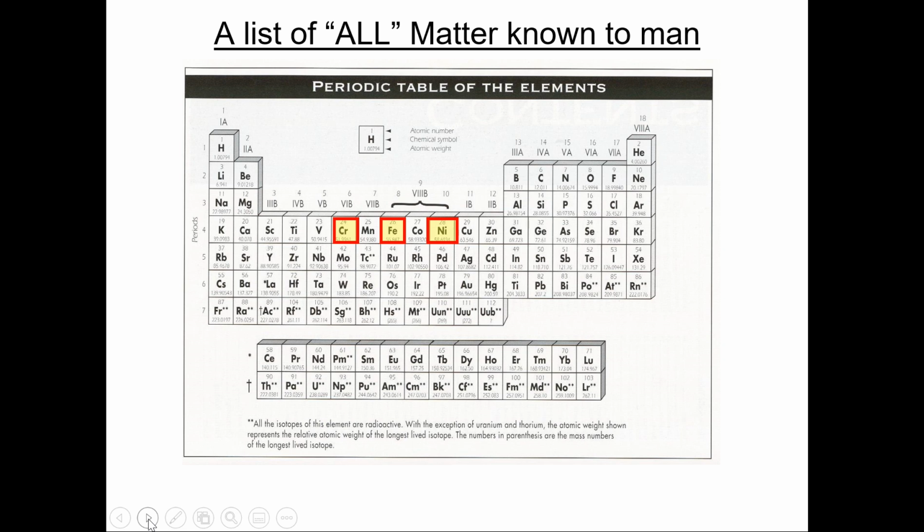Now nickel works as a really good joining element. So if we have a lot of nickel in a filler material, it's very good at joining tool steels. Now remember this about nickel. Nickel will not harden. 300 series stainless, this type of stainless you see in your sink, the type of stainless that's nice and shiny for the really good barbecues. All these stainlesses, they cannot be hardened. The nickel content won't allow it to happen. But because of that property, one of the things it does well is that it'll weld high carbon materials, and the weld itself won't be contaminated by all the extra carbon or chrome. It doesn't care. The nickel keeps everything soft.